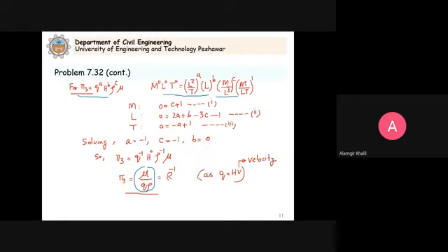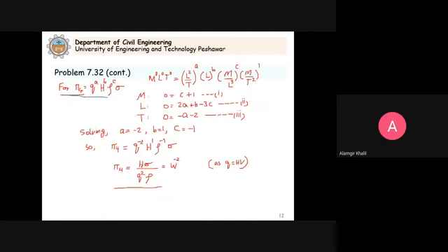And also you need to identify the familiar dimensionless numbers. For example, this is the Reynolds number. Similarly, we go for pi 4. We put the dimensions and then we determine the values of these arbitrary exponents or powers that we assigned and we simplify here. Again it turns out that this is equal to the negative square of the Weber number. Clear? This is how we can identify the dimensionless numbers that we are familiar with.